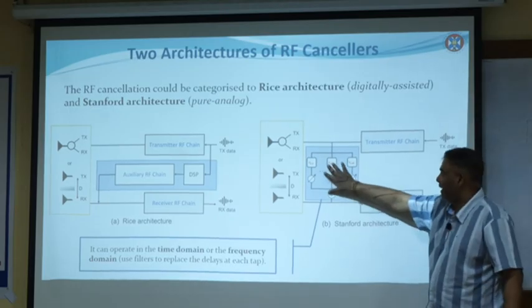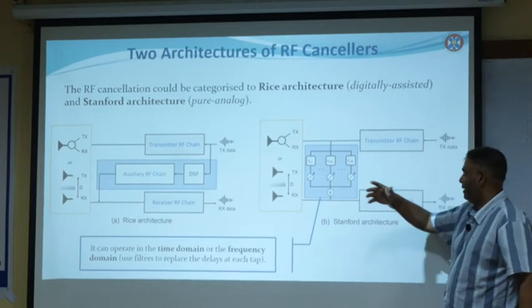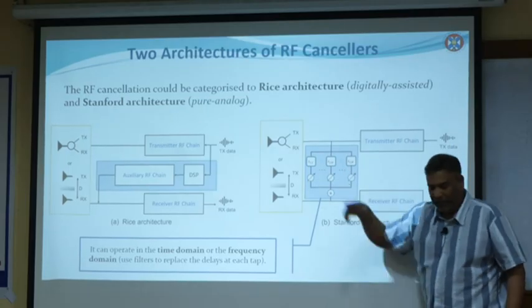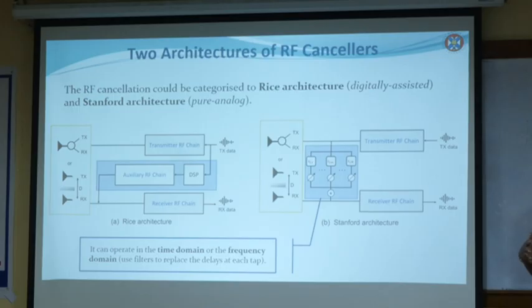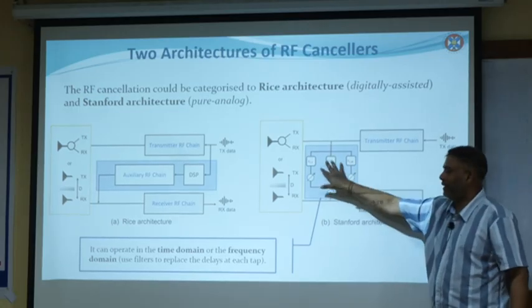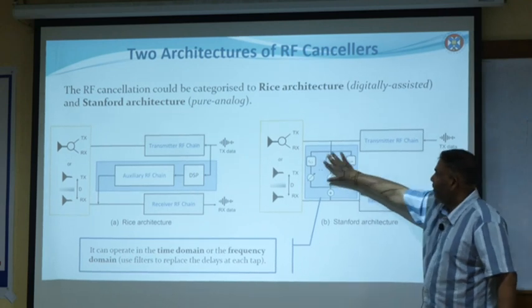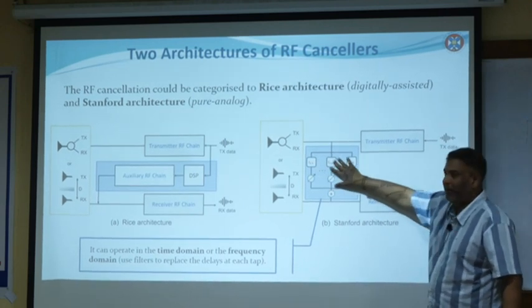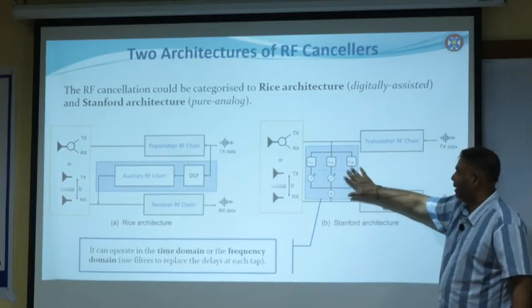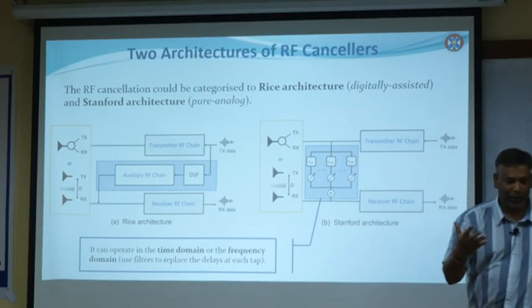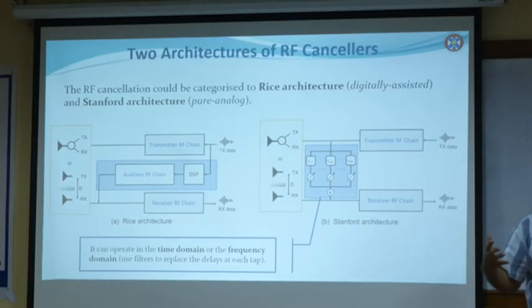We came up with a technique called optical domain cancellation. Because if you have a 400 megahertz channel, the channel is more frequency selective. There will be more taps needed. If we use a microstrip-based analog cancellation circuit, we won't be able to create a multiple tap channel.